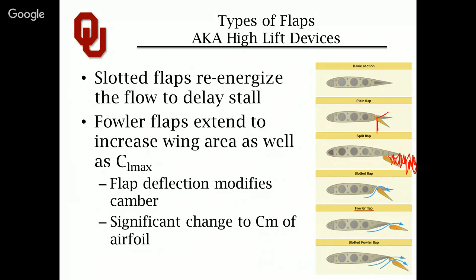But I say they're a little bit cheaty because they bookkeep their CL without telling anyone. They just increase the chord of the wing. Look at all the other flap scenarios here. So the basic section has so long. Whenever this Fowler flap is retracted, the airfoil might be 1 unit, but whenever they extend it, it actually moves mechanically aft. So the chord length of the airfoil changes.